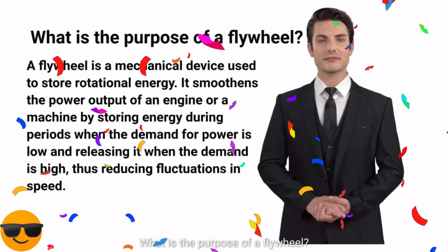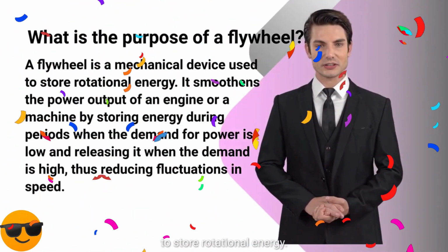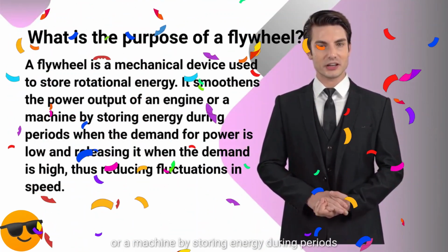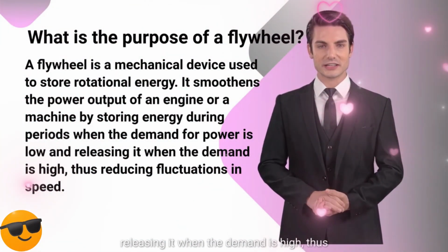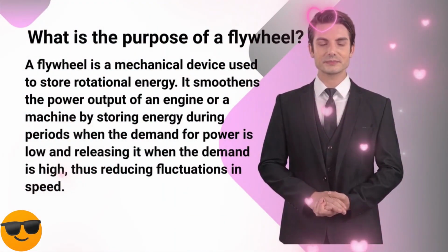What is the purpose of a flywheel? A flywheel is a mechanical device used to store rotational energy. It smoothens the power output of an engine or a machine by storing energy during periods when the demand for power is low and releasing it when the demand is high, thus reducing fluctuations in speed.